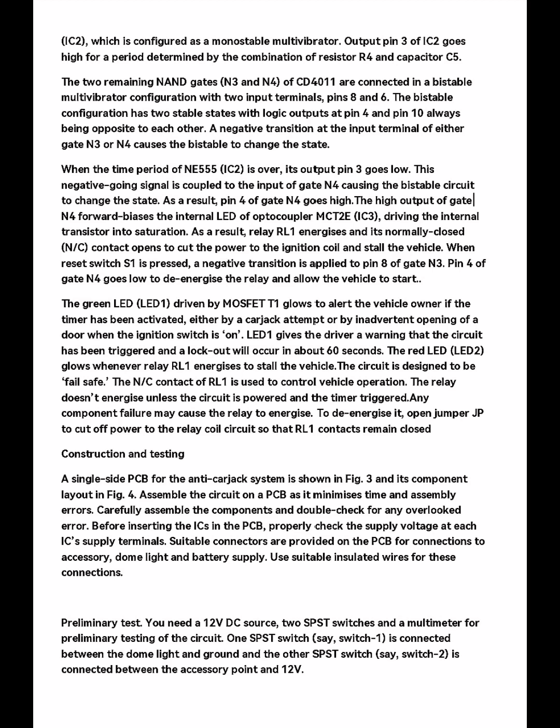The bistable configuration has two stable states with logic outputs at pin 4 and pin 10 always being opposite to each other. A negative transition at the input terminal of either gate N3 or N4 causes the bistable to change state. When the time period of NE555 IC2 is over, its output pin 3 goes low. This negative-going signal is coupled to the input of gate N4, causing the bistable circuit to change state. As a result, pin 4 of gate N4 goes high.